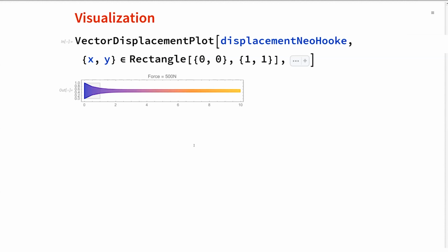The advantage of that approach is that NDSolve has an adaptive step size mechanism. So it will take the exact steps that it needs to get to a new solution, while with the solver restart, we've just specified the steps manually. The solver restart may be a bit simpler to set up, so it's a good initial try. If that fails, you can still go ahead and use the time stepping.